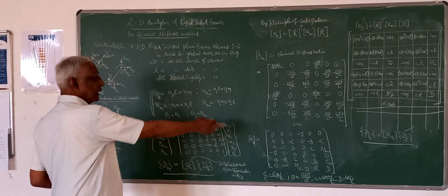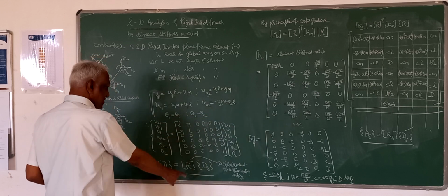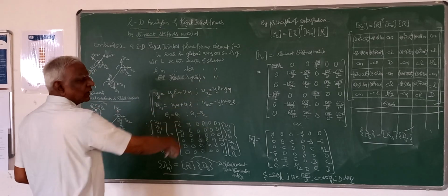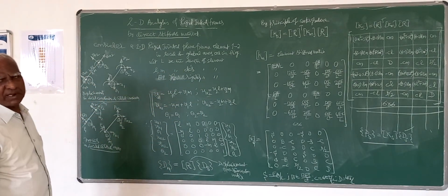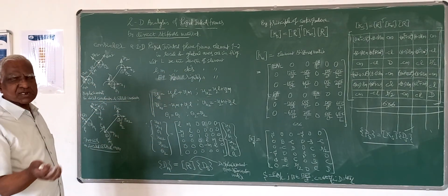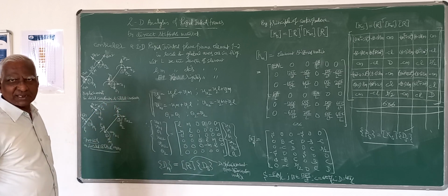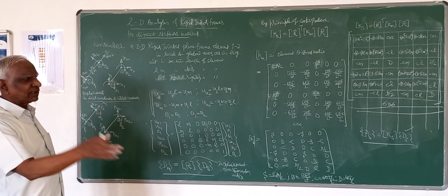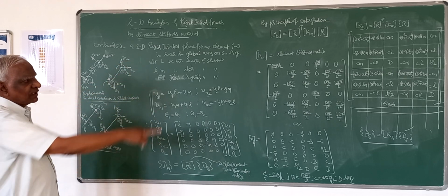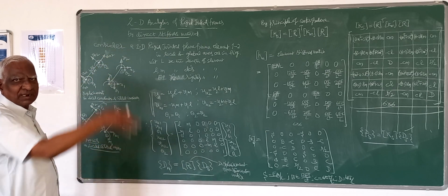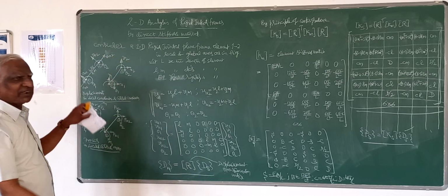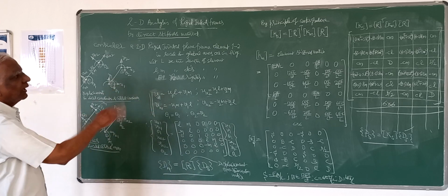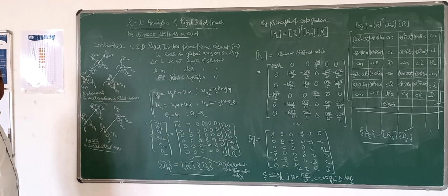So straight away, after converting the ds to dm and then knowing km and dm, we can find out the element member forces. Or you can use the slope deflection equations directly, which give the moment in terms of displacements at the ends, the slope, as well as the relative translations V1 and V2 at the ends. So knowing that slope deflection equation, we can calculate the member end forces.